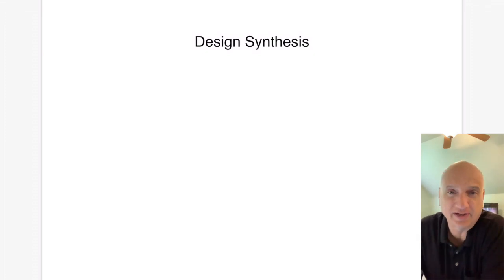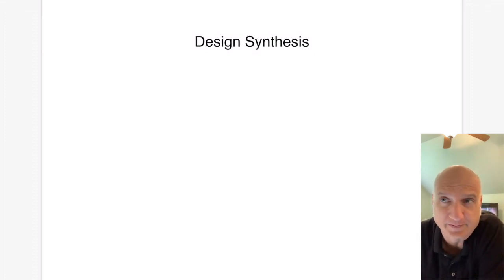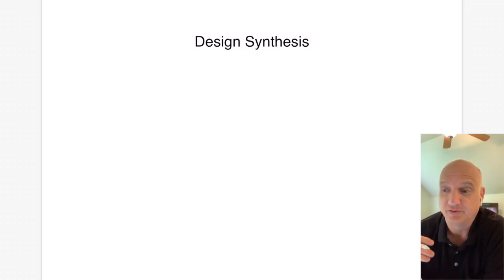Okay, gang, now it's time to talk a little bit about design synthesis. Synthesis is a fairly new term for folks who haven't been around VHDL or the FPGA world. It is quite simply taking a design and mapping it directly to hardware. The idea is you describe hardware in words, and then a synthesizer reads those words and interprets them in terms of gates, registers, multiplexers and all kinds of other devices inside your digital design. So that's what a VHDL file does.